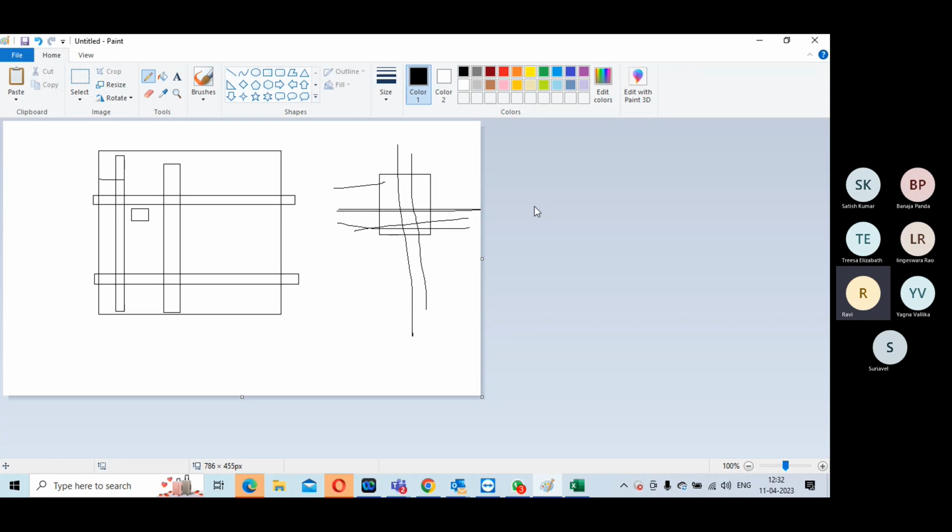Power gater, similarly isolation, I want to tell you so many things. Power gaters should align vertically and horizontally so that whenever I am drawing a mesh, I can directly hook like that. Orientation should not be switched. If vertical side, the orientation should be the same, because then the pins will be exactly aligned.